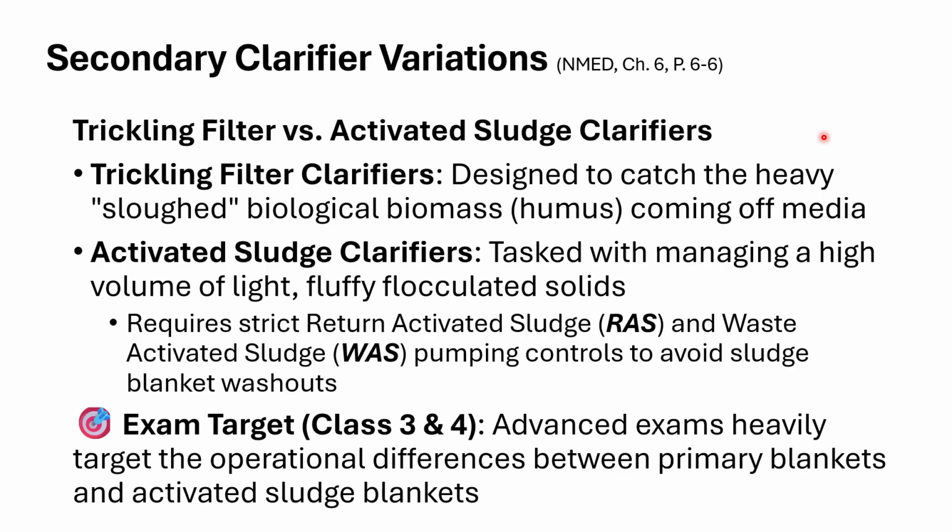So another thing we want to look at, we talked mainly about primary clarifiers, but let's look at secondary clarifiers. Recall that a primary clarifier, the idea there is to let the heavier solids settle out of the wastewater stream and let the lighter organics, fats, oils, greases float to the top of the surface and get skimmed away. It's basically a physical type process, sedimentation, flotation.